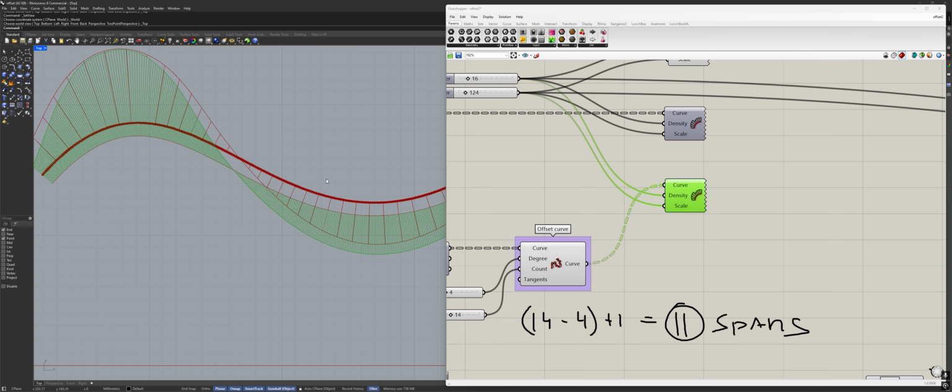But even if there is enough room, like here, maintaining the proper distance and at the same time keeping the curvature as it was becomes an extremely challenging task, especially when we're talking about complex surfaces. In curves, it's a little bit simpler, and Alias can actually get you covered with that, and we will talk about that in a bit. But this is the overall limitation and the problem with an offset in general.